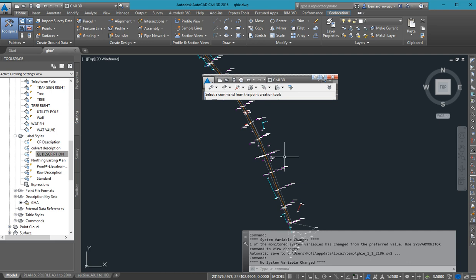So depending on the situation, but in this case with an existing road, we will ignore the invert level. If not, we'll have drops wherever there's a culvert. What it means is that at the end of the day, our earthworks volumes will be higher than normal. Please, are we getting it? Because wherever there is an invert, it will also have to compute from there.